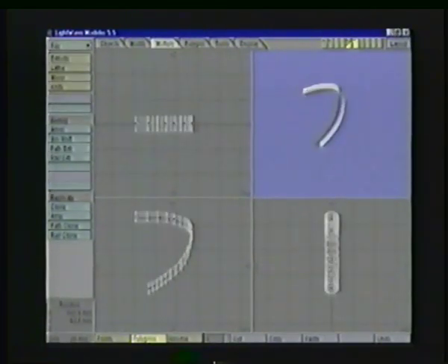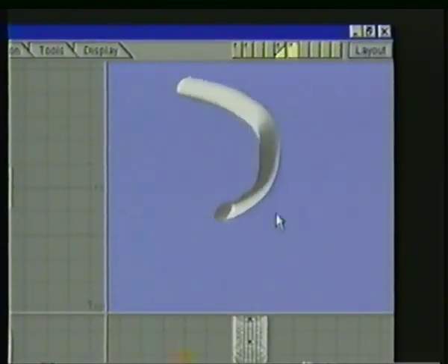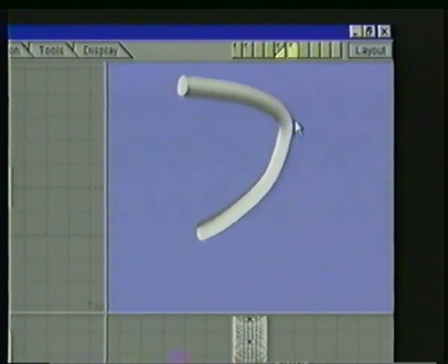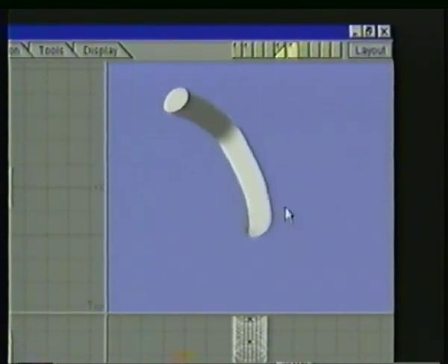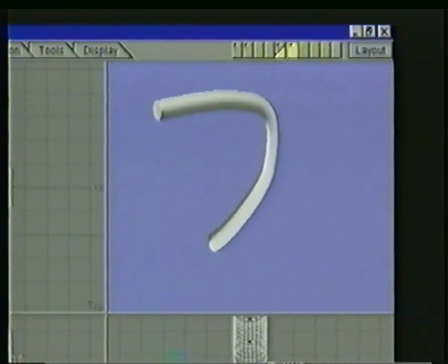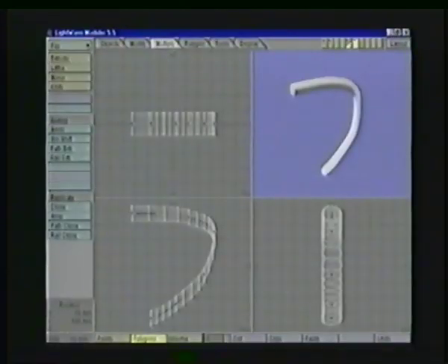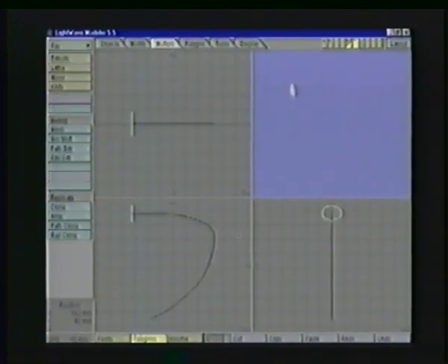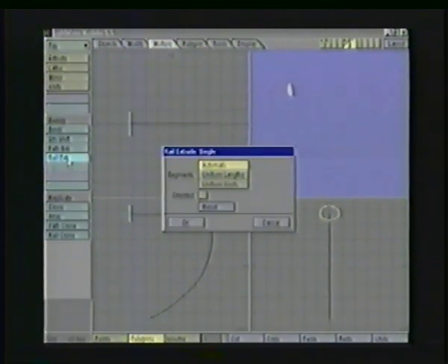So if we look closely at that, it starts off just fine, flattens out, and turns inside out. Because it's keeping the polygon that's being extruded straight up and down as it's being dragged along the curve. So in this case, we want to be oriented. For now, let's just go with a plain, vanilla rail extrude, automatic, oriented, pretty much the default setting.